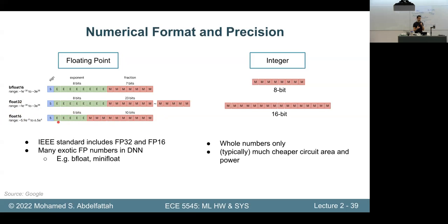Roughly, for multipliers, you have a quadratic growth with the number of bits in your number, so you would have much smaller multipliers when you implement them on chip. 4 times as small, because there is a quadratic relationship. For adders, you would get a 2x reduction in size and a 2x improvement in efficiency. So reducing these numerics really helps.